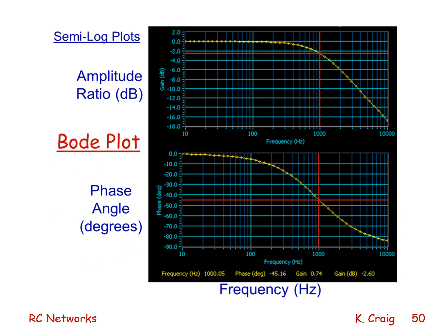Here is the Bode plot from the myDAQ. Now, this is a particularly useful virtual instrument, the Bode plotter, because to do this manually would take quite a bit of time, as for each data point shown, I would have to input a sine wave from my waveform generator into my RC circuit, look at the steady state output sine wave, calculate the amplitude ratio, convert it to dB, and plot it.